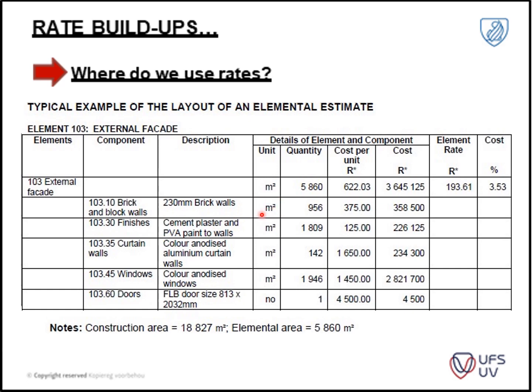You will see brickwork is measured as a per square meter rate, but you might have the instance where you have to include your reinforcing or brick force, which is usually measured in meters and with the size provided for it. So you need to calculate how many layers of brickwork there are, and then it is translated into your rate and subsequently your cost.